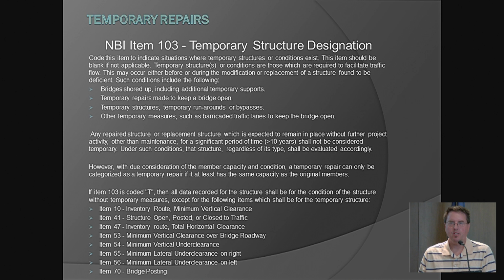If you intend for it to be a permanent repair, we highly recommend that you either remove the old member or you alter it in some way that it is no longer part of or looks to be part of the load path.